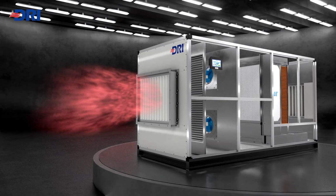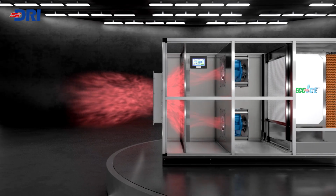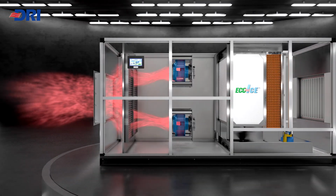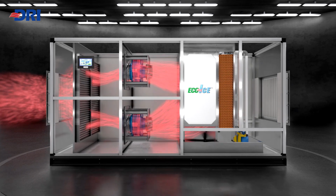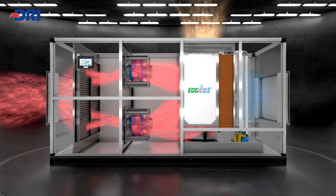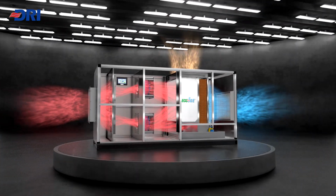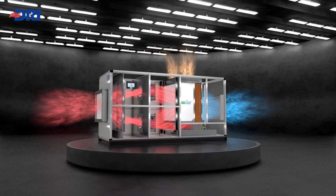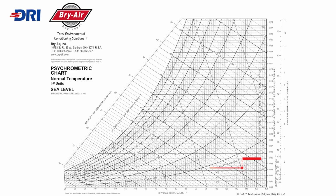In the first stage, the heat exchanger ensures the air is pre-cooled without adding moisture. This lowers the air temperature significantly before it enters the direct evaporative stage. Since the air is already colder before reaching the water-saturated pads, it undergoes a second cooling phase that pushes it below the wet bulb. This innovative approach enables IDEC systems to achieve sub-wet bulb temperatures, delivering cooler, more comfortable air than traditional evaporative cooling methods.